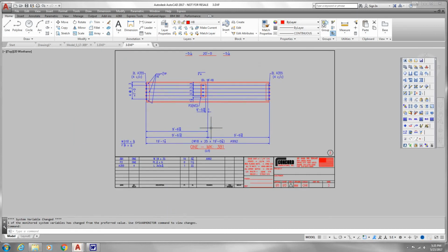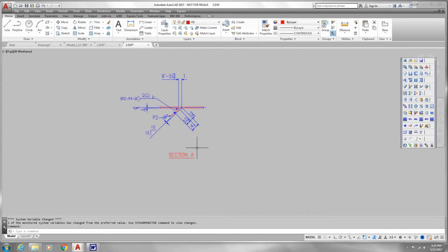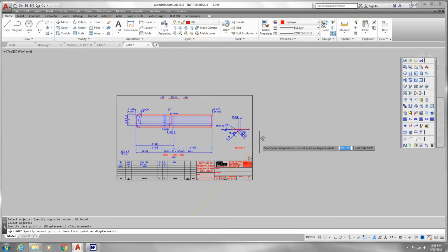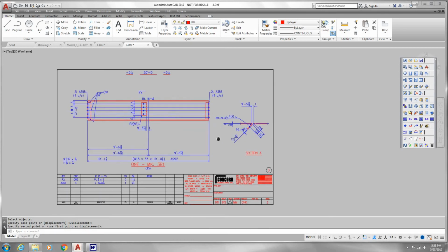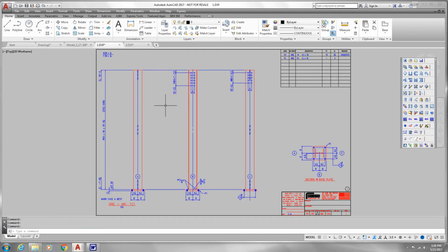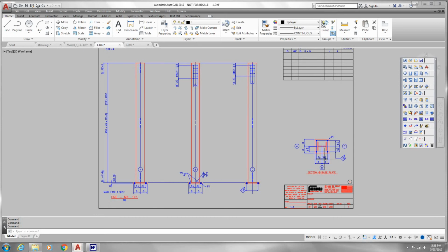Okay, here's the beam sheet showing the shear tab, and here's the layout of the shear tab. We throw it down off the sheet there so that you can just move it wherever you've got room on your sheet to keep it from having any overwriting cleanup necessary. Okay, and the column, fairly simple column. There's our base plate. Here's the layout of the base plate.